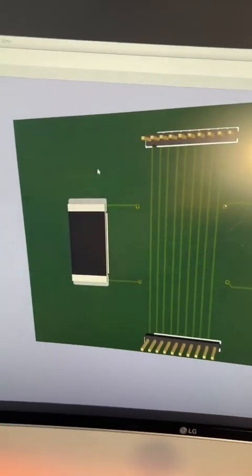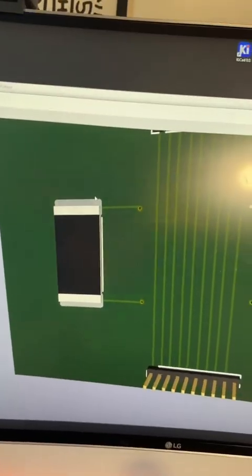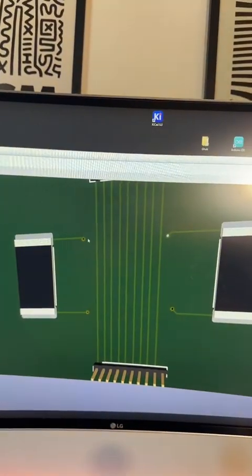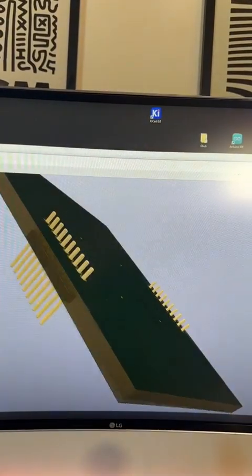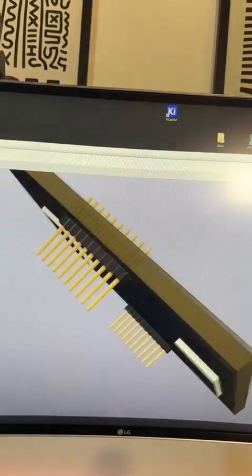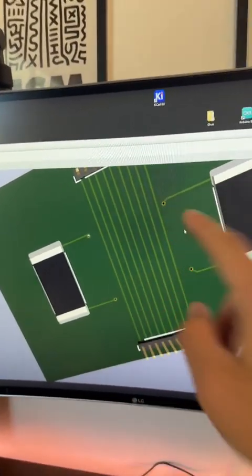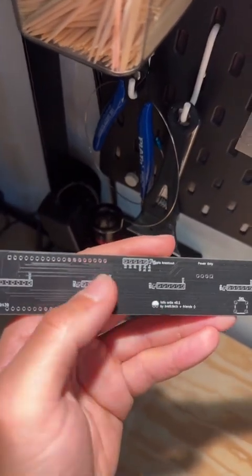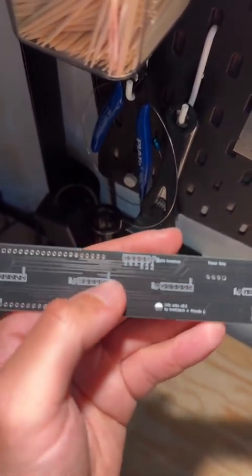So check this out. This is the top side of our PCB. You'll see we have our resistors here, and there is a trace going over to where we'd normally need to cross over. But it jumps down to the bottom of the board, hops over that set of wires, and then resurfaces on the front. So we can still have these top mounted components without having to interfere with all these traces. I use these in plenty on my InfoOrbs PCB. They're very subtle in real life.